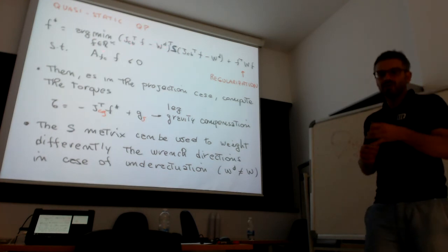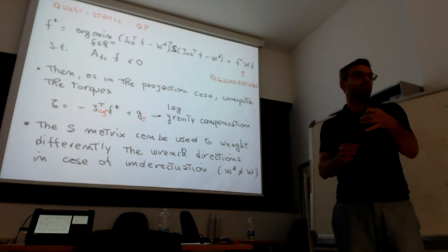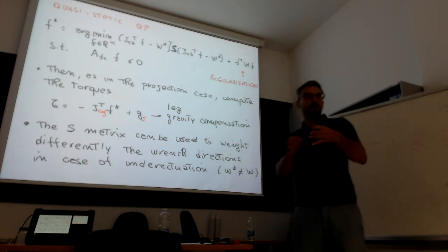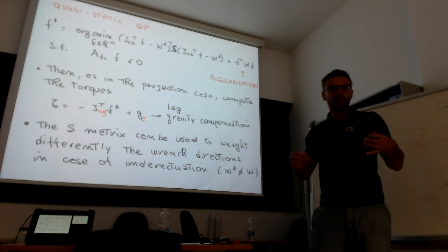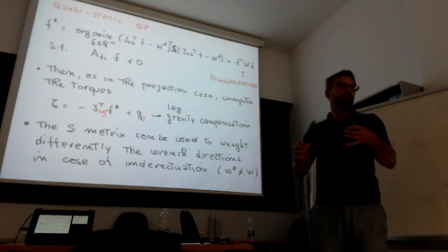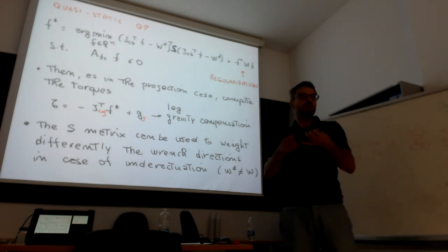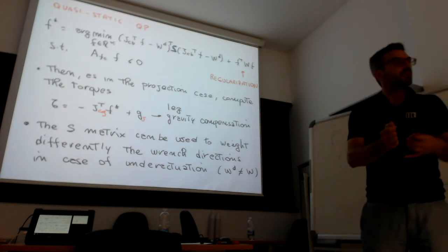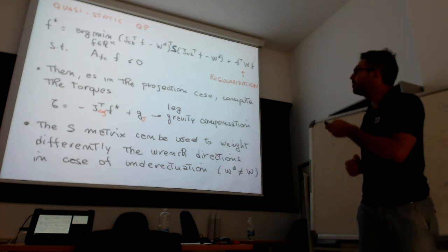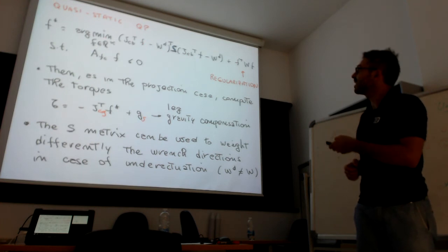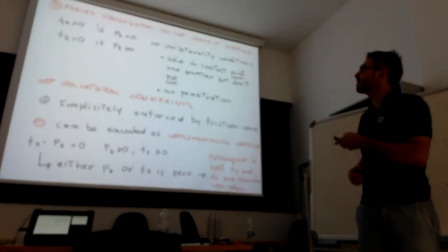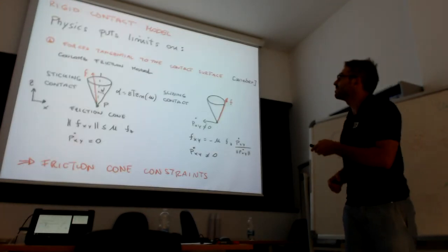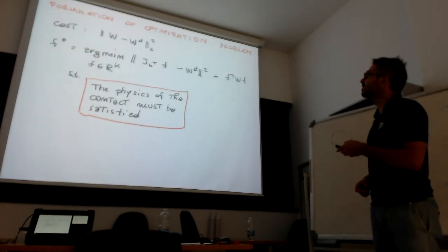So if I have a desired trajectory coming from the planner, but if the actual COM goes away because of a push, then it creates an error in the virtual spring, and then this spring creates a force to attract back to the trajectory. So the compensation is not here, it's inside the feedback controller, maybe that was not clear, it's inside the virtual model.